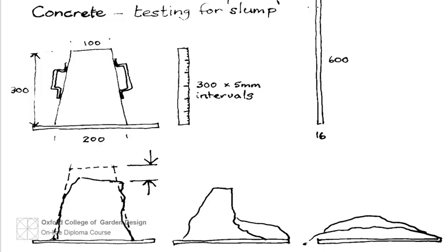The shape should be a gently shelving side and bottom with no abrupt angles. It should be dug out, and any large stones, roots and rubbish, etc. must be removed before the surface is smoothed and compacted. Use galvanized 20 mm hexagonal wire mesh, folded and cut if necessary, to lie smoothly on the excavation. Tie the cuts and folds securely with galvanized soft iron wire.